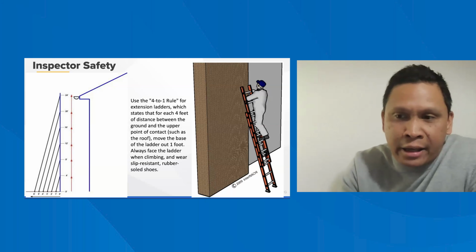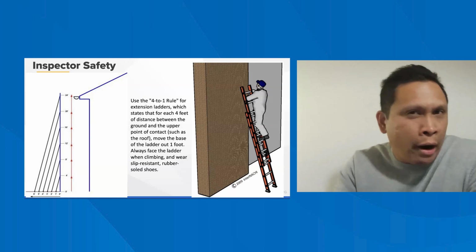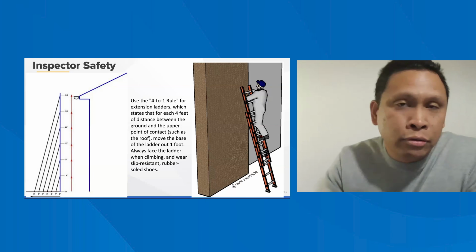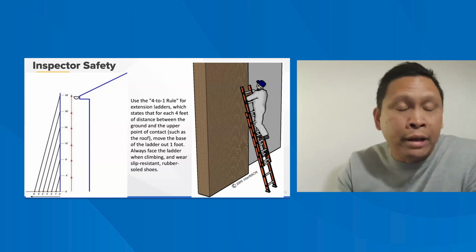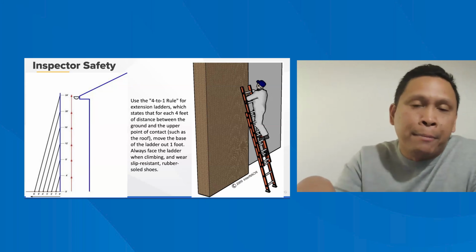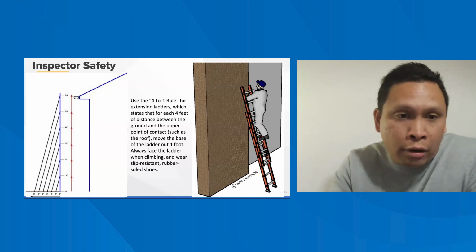When you're in the attic, there are a lot of different safety concerns. Are we required to walk through the attic? No, right? Most of the time, depending on the house that you're inspecting, there probably isn't a floor in the attic, so it's dangerous to walk through it.